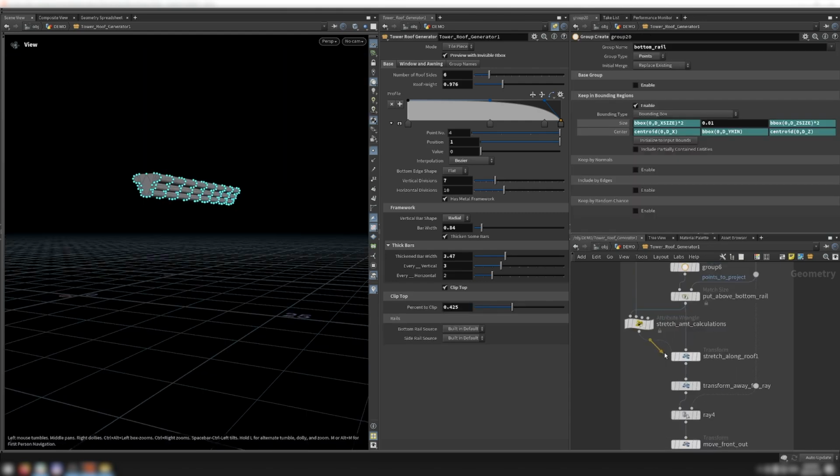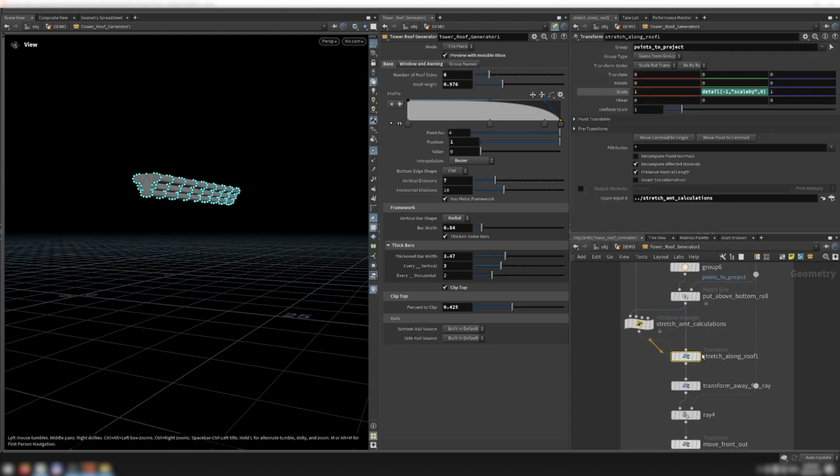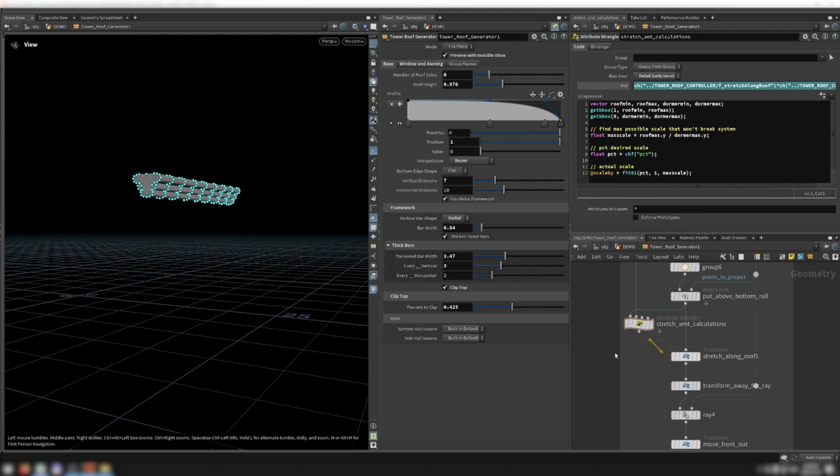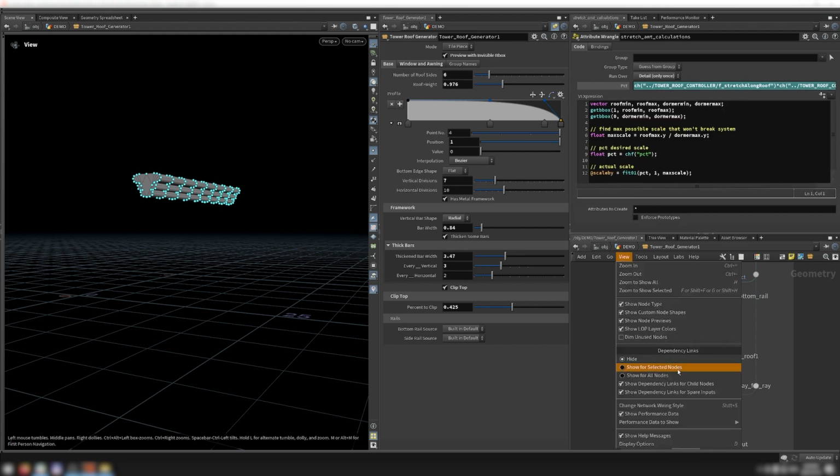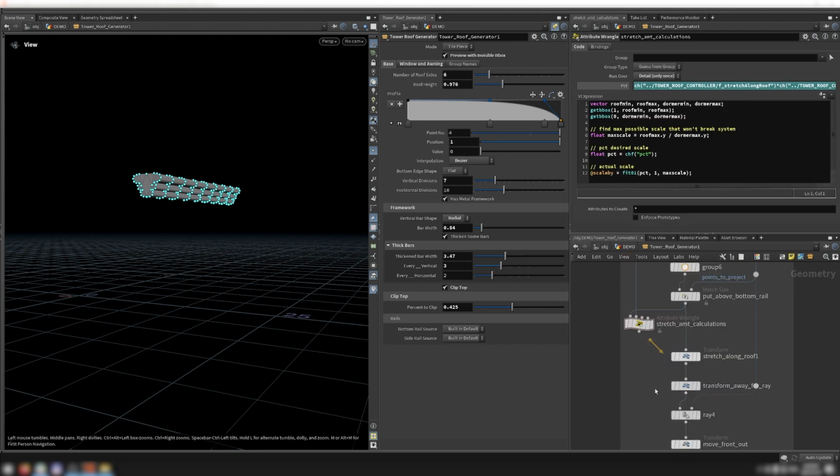You'll notice I included another sticker here, because this node uses this node as a spare input. I don't love that if I happen to have dependency links for spare inputs turned off, without this arrow it's unclear what this node does, and it looks like it might not be in use at all. To make sure this is always clear, in cases like these, I like to add a little arrow sticker, so the node doesn't get accidentally deleted.